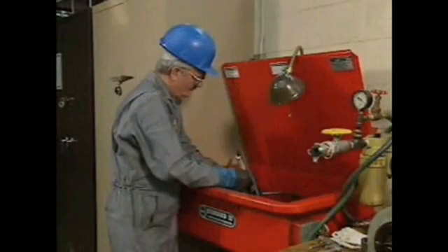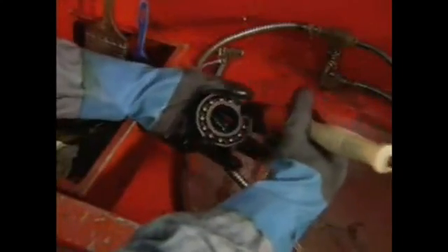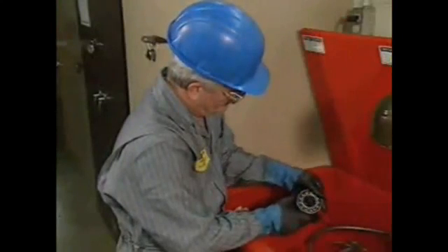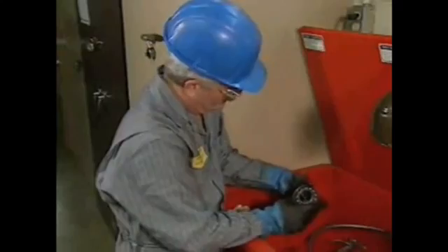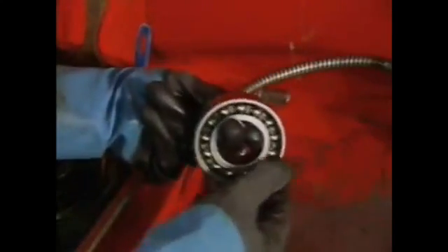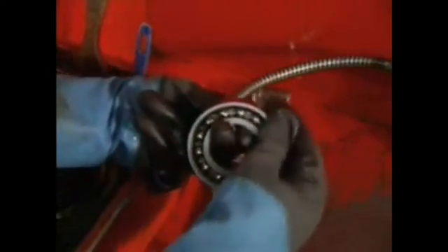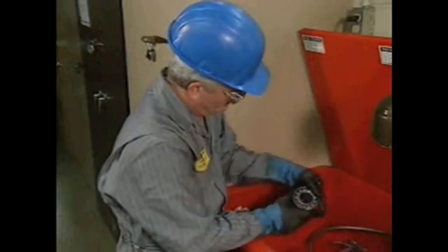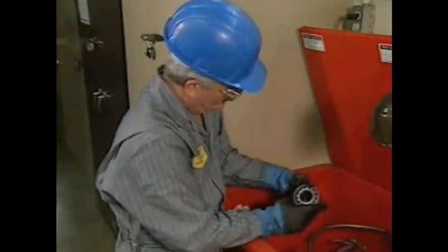In order to properly inspect the bearing, the mechanic must first clean it. In this example, the mechanic cleans the bearing with an approved solvent to remove grease and dirt. Then, after the bearing has dried, he examines the bearing for signs of failure. He turns the bearing slowly to determine whether there is any stiffness or binding when the rolling elements turn. He also checks for signs of failure such as spalling, burn marks, cracks, dents, and pits.